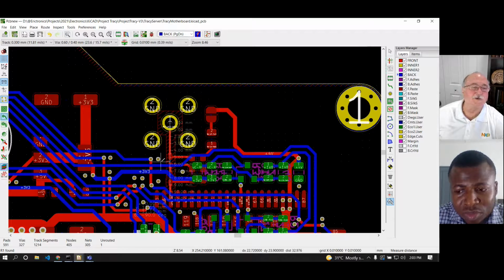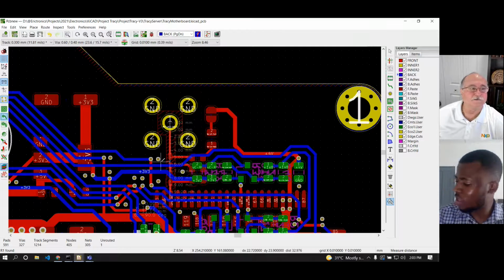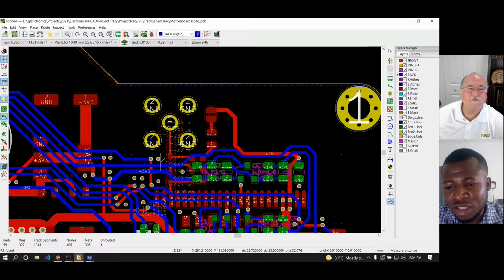Your challenge is just to make sure that you know how wide those traces need to be, based on the thickness of your dielectric, to get your 50 ohm transmission line. I did the calculations with a JLCPCB tool. I think I had about 0.293 for a 50 ohm impedance trace. Those impedance calculators are all pretty good.